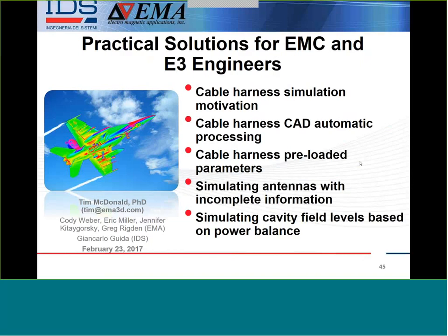Again, we talked about some interesting tricks for modeling cable harnesses that bring the time for that simulation down from weeks of man-hours to maybe a few days, targeted days. We've got ways to model antennas when we have the incomplete information that we always get on every project. And we've got ways to do the field coupling to cavities, again, with incomplete information up to frequencies that you can't get to otherwise.